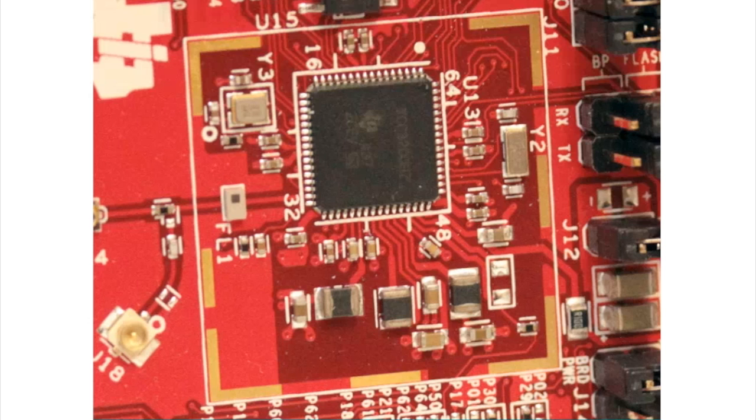So as I mentioned earlier, manufacturers charge you per component to produce your IoT devices. More parts means more expensive setups. More expensive setups can be mitigated by scaling up your orders, but only to a point. If you can't manage all of this, your cost per node is going to start getting out of hand. So the key takeaway to this point is to get intimately familiar with the data sheet and the reference implementation of all of your primary and most expensive components, especially your wireless piece.